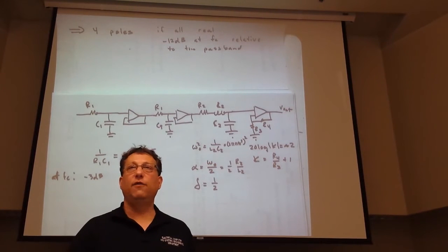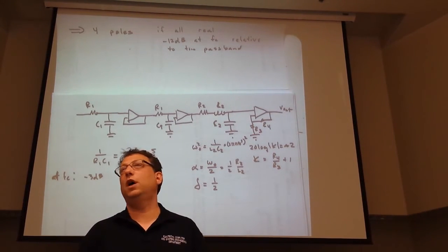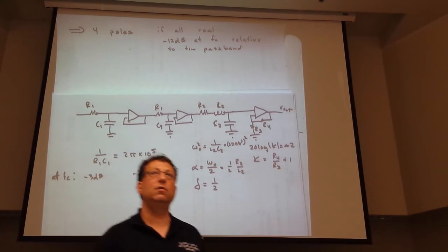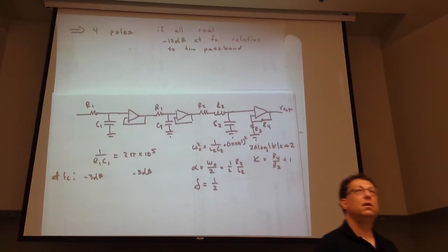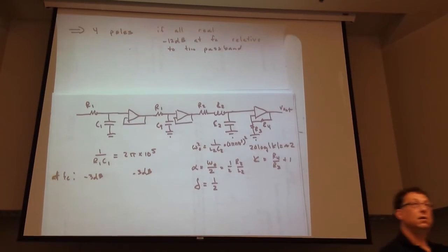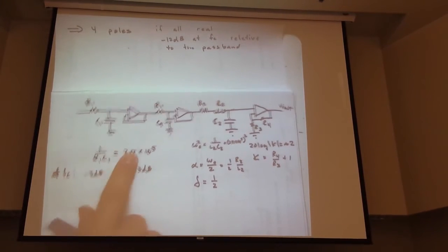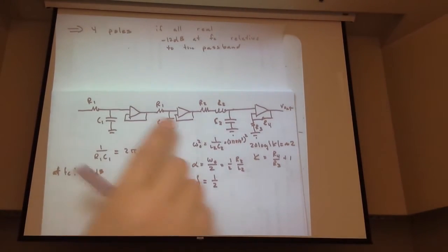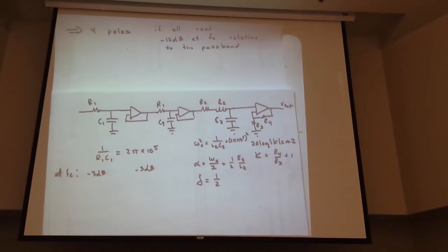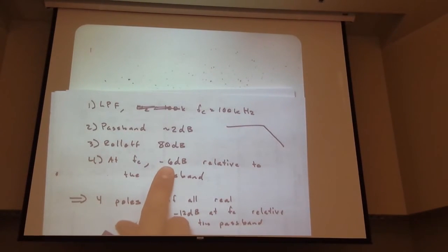Just a second. If it was minus 3 dB, what's our damping ratio? This is one we want to be familiar with as well. 1 over square root of 2. Why couldn't you use an overdamped circuit? No, you could. Oh, here? Well, if this has a damping ratio of 1/2, and if you replace this with an underdamped circuit as well, then our correction is going to be above minus 6 dB.